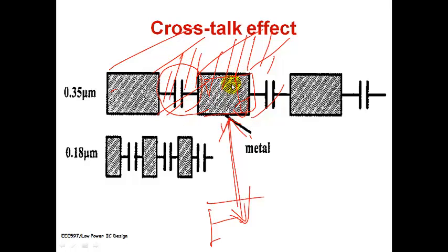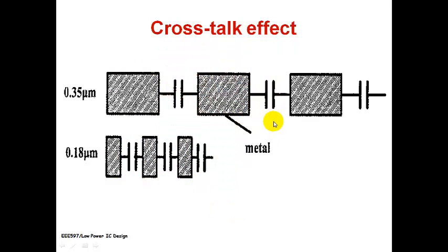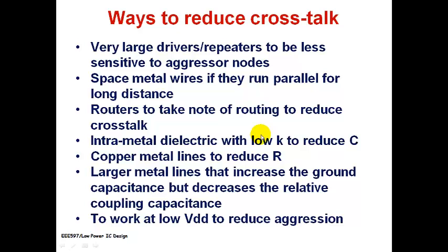Why do I make this so tall? Because I want my cross section to be high enough to bring down the resistance R, and this process ultimately creates so much sidewall capacitance and area capacitance. These are the things that have to be tackled also, and these are the research issues we have with us when we go for interconnect theory.